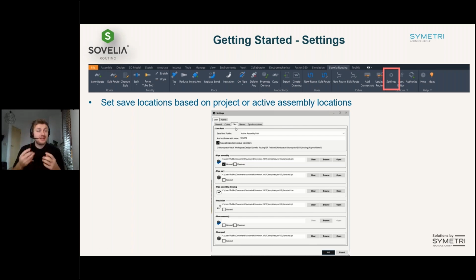So we might actually want to set it to phantom so that we're not including in the bill of materials all of the pipe information and all of the bend information. We just want to show that it will still be included in the mass calculations and things like that to pull through to our top level. Okay, we just want to show the overall pipe assembly and then show that on a different drawing.